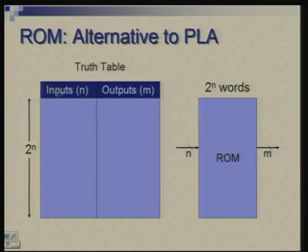So these n inputs which you want to apply to the combinational circuit you are designing, you apply as address to the ROM, and you read out the contents of the addressed word. So it effectively works out as an n input and m output combinational circuit. The definition of the function which this implements is directly given by the output columns of the truth table. So each row of the output part corresponds to one word in this memory.